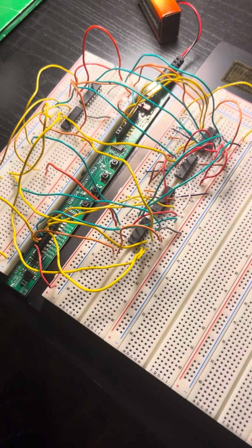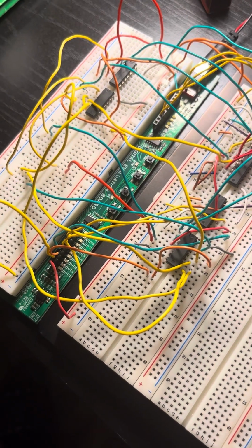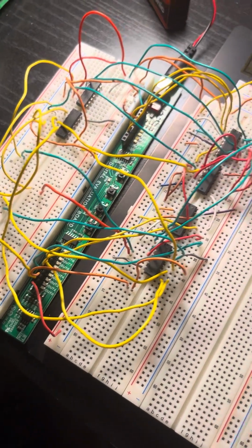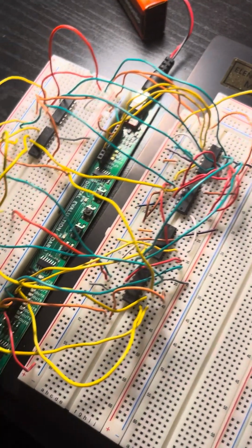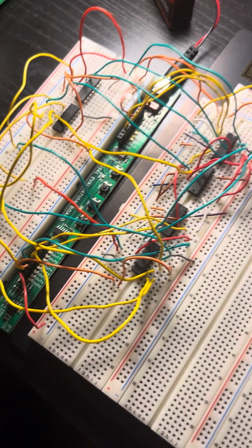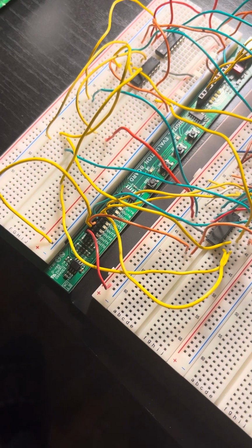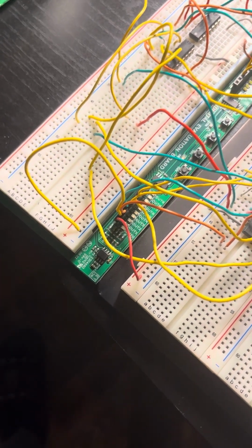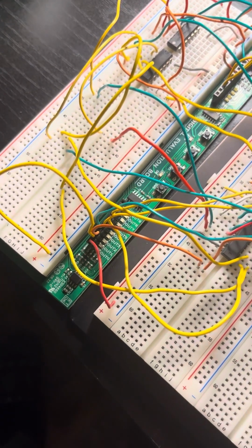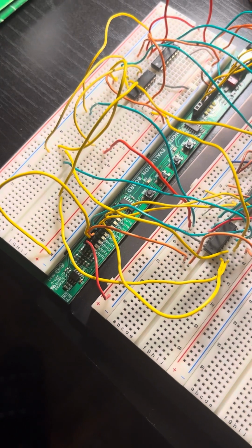Now the address bits that I used were input 0, input 1, and input 2 on the digital evaluation board, with input 0 being my most significant bit into my decoder and input 2 being my least significant bit. I displayed the ASCII bit outputs on output terminals 0 through 6, with output 0 corresponding to the first ASCII bit, output 1 corresponding to the next ASCII bit, and output 6 corresponding to the last ASCII bit.